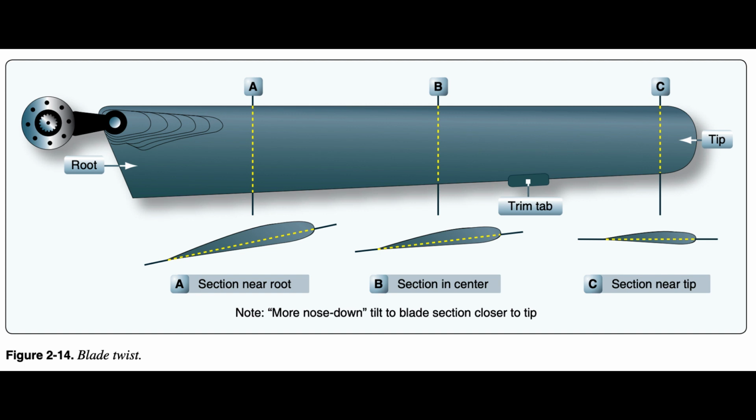1. Hub on the mast, the attaching point for the root of the blade, and the axis about which the blades rotate. See Figure 1.7. 2. Tip, the farthest outboard section of the rotor blade. 3. Root, the inner end of the blade and the point that attaches to the hub. 4. Twist, the change in blade incidence from the root to the outer blade.